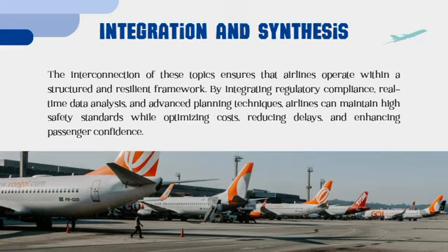The IFR chart application guides the use of IFR charts for navigation, approach, and departure, tying into flight planning and execution. The route optimization in IFR planning covers strategies to save fuel and time while maintaining safety, showing how tools and technologies optimize routes. In weight and balance, we demonstrate how improper calculations can jeopardize safety, with examples of impact on performance.